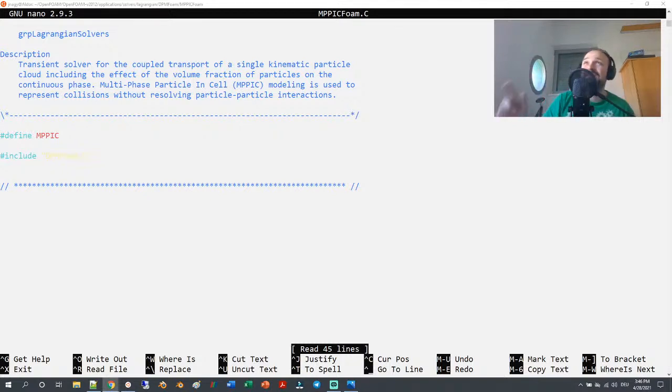If it is an internal flow, you know what should go out of your geometry, so what's the mass flux that your geometry has, which leaves the geometry, and then you calculate the actual value on the outlet, and then you see the difference. But to see whether there is a backflow, that is very simple with glyphs and vectors. To quantify, that's something that I would have to think about myself.